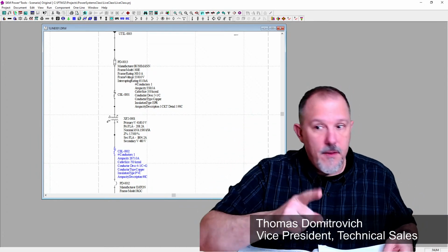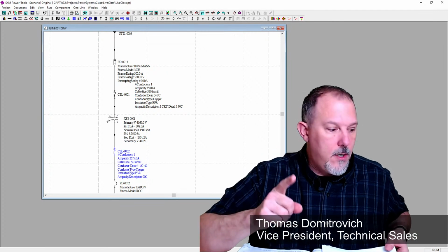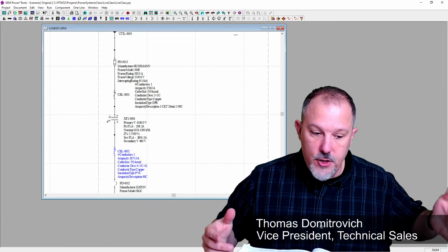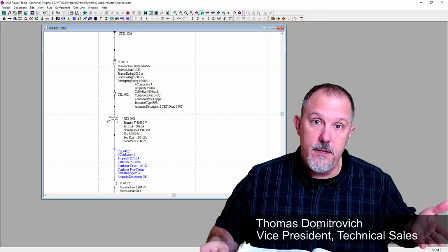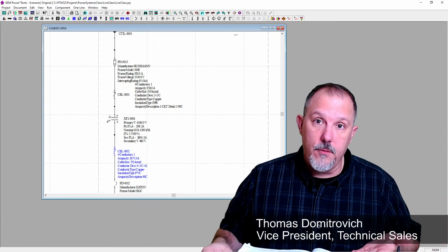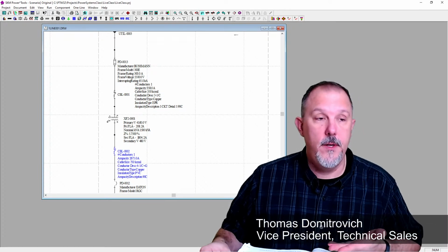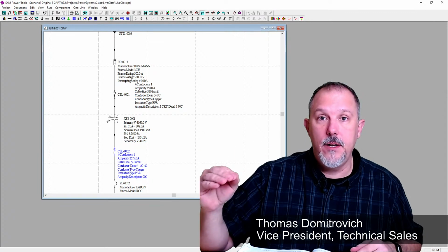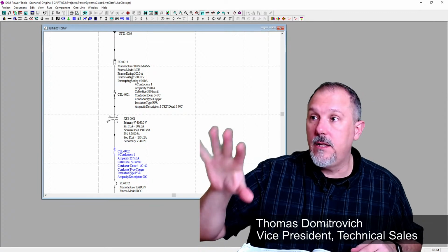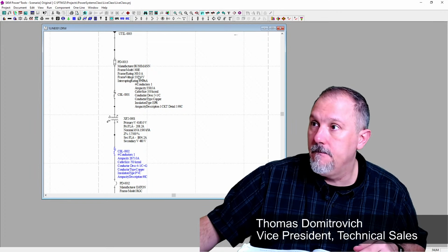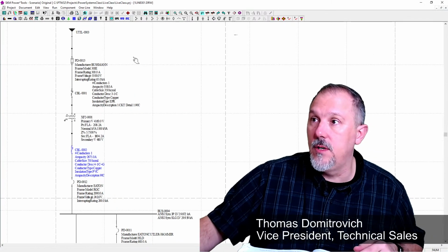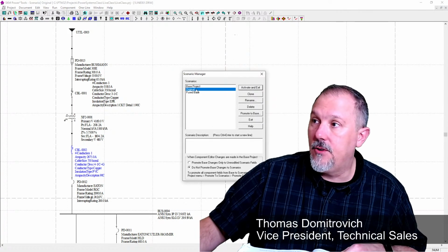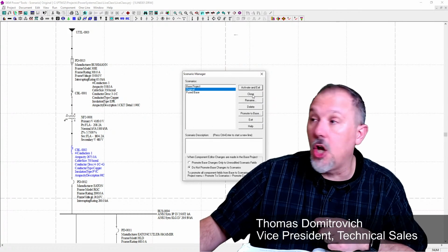So I want to cover that, and I'm going to work through a conduit fill calculation, and I want to work through an ampacity calculation, and then we'll make some adjustments to this. We'll make a scenario. We'll take this one line right here, and I'll show you. I'm going to go Project, Scenario Manager. I grab the original and I say clone.